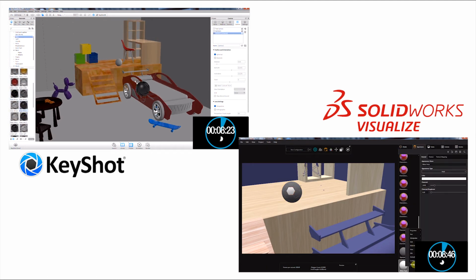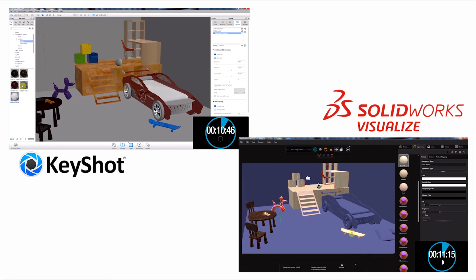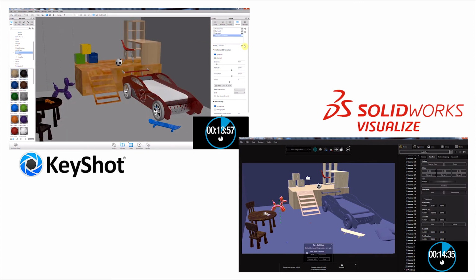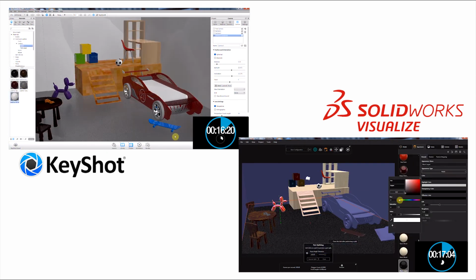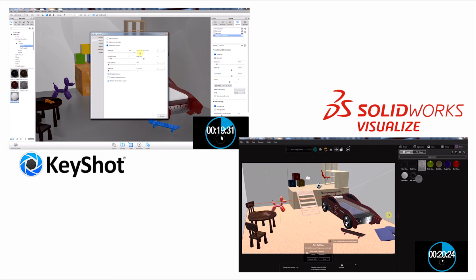The quality of the materials and appearances is where I found that SOLIDWORKS Visualize really had the upper hand, especially when it comes to post-processing. When you apply a material in Visualize, it tends to map really well, where in Keyshot it takes a bit more adjusting, and especially the wood materials seem to be low quality, so I can't quite get the grain the way I want it. Materials are easy to find online and modify for any rendering application, so this really isn't a huge deal, but if you want something that works directly out of the box, I would go with SOLIDWORKS Visualize for the appearance and scenes.